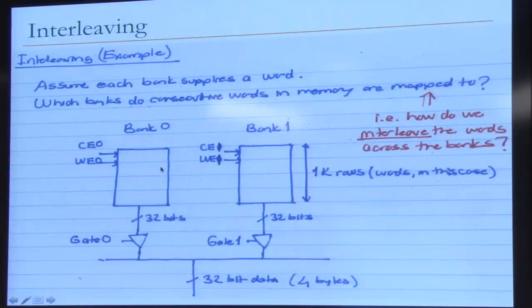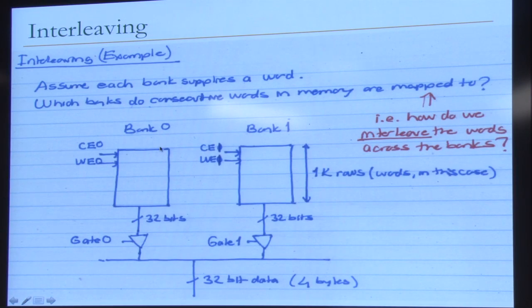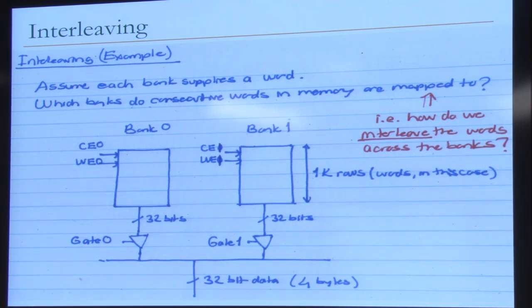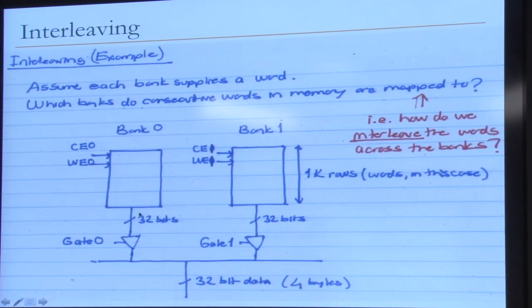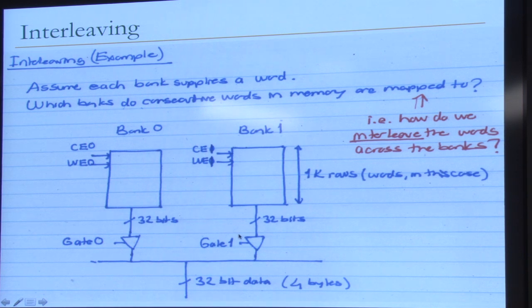That's page level interleaving. Now you can actually think about different granularities. You can think about the top half of the memory address space mapped to this bank, and the bottom half mapped to this bank, right? That's bank granularity interleaving, if you will. OK? And this is a nice way of looking at the bank. Basically, these are two banks that share the address, command, and data buses. Only one bank can load the data bus at a given time, but you can pipeline the accesses. This is what we had seen when we talked about GPUs, for example, when we talked about vector processors.